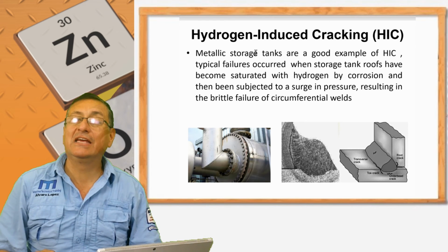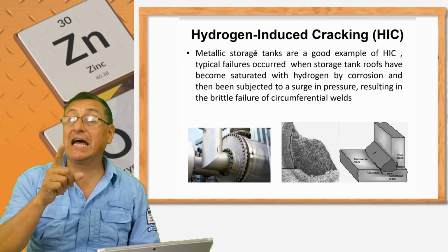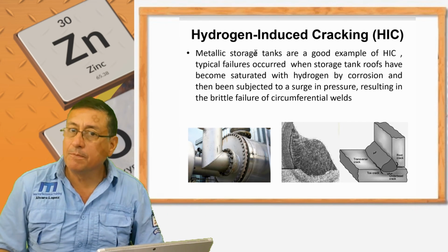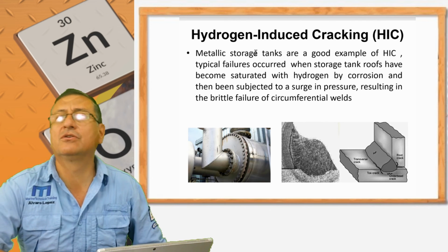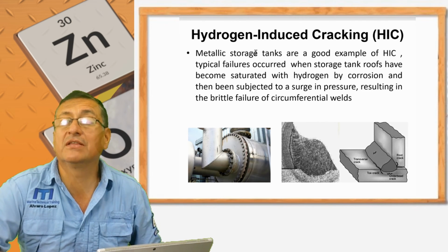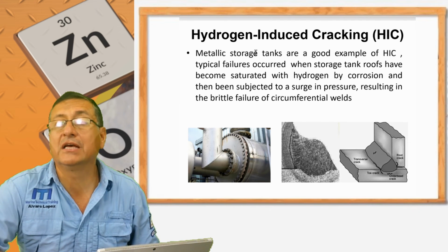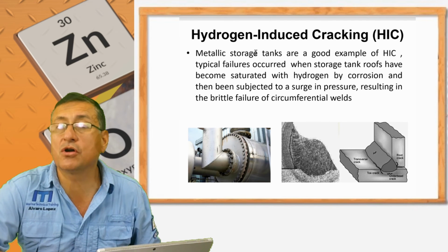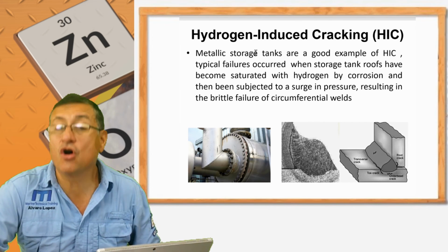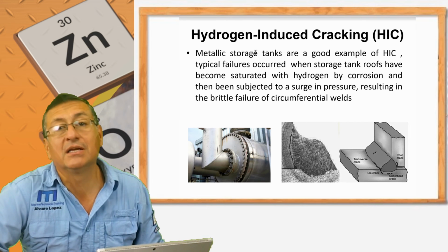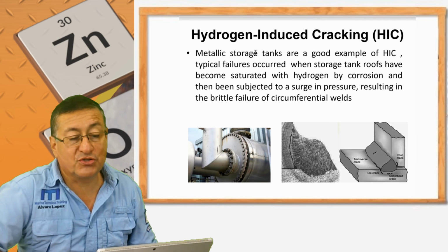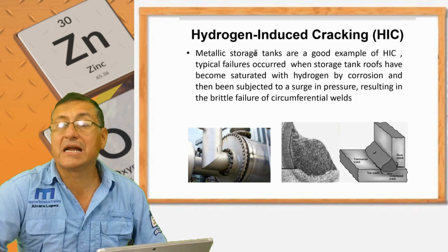Normally in the exhaust pipes of a dry exhaust pipe system. You remember in our diesel course, in keel cooling systems, the advantage of the keel cooling system is that you don't have raw water inside of the boat. In that case, the smoke is dry smoke, and you can use a regular exhaust pipe. Be careful with the material of those regular exhaust pipes, because it should be marine grade. If not, you have that type of corrosion, hydrogen-induced cracking.